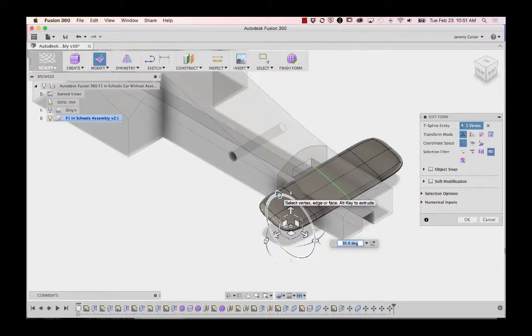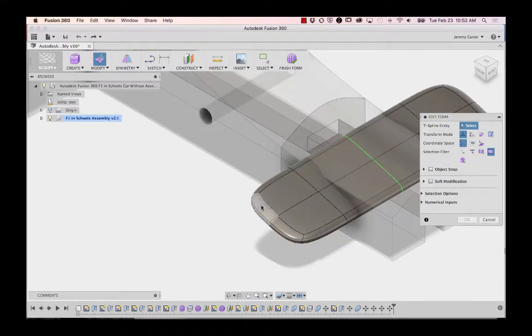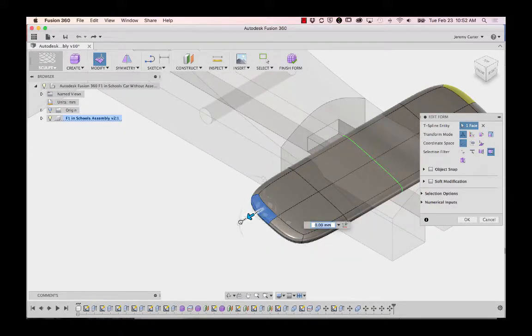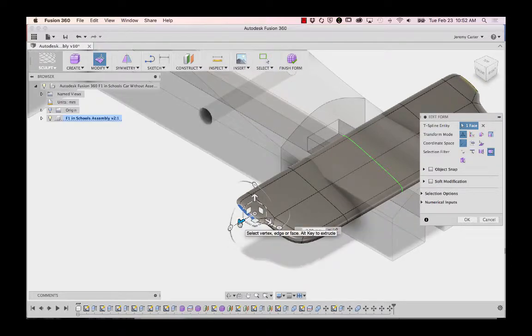Notice the different effects? Make sure you click undo and go back to the original shape. The Edit Form window allows you to narrow down the selections. Let's select this left rectangle here. Hold down the Alt key and drag the left translation arrow about 3 millimeters. Holding Alt adds new geometry to the shape, so you can create complex shapes. Dragging without Alt just changes the original shape.